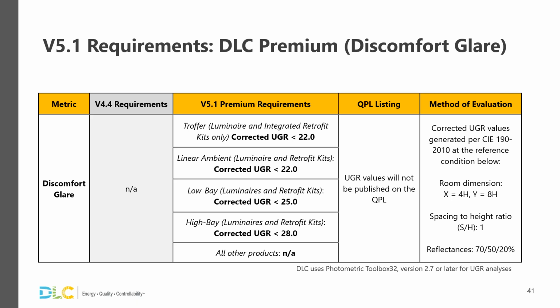Please refer to the additional reporting section in version 5.1 for more requirements and guidance for IES files as they relate to UGR. One important note that I want to mention here, the UGR requirements do not have any additional tolerances. Each maximum requirement for UGR within each PUD already includes a buffer within the 3-step change in acceptability. This is true here and in the allowance sections. For those wishing to unlock efficacy allowances, there are more stringent UGR requirements later. We'll be discussing them soon.